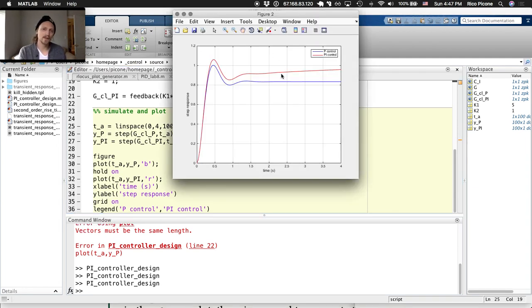Yeah, so it's going to 0, but it's slow, right? The transient happens and then it slowly oozes back to 0 steady state error, probably at time infinity. So we have success: 0 steady state error, and transient response performance that we started with, which is about 20% overshoot. So that's all good, but we might say we'd really prefer to settle to our steady state value a lot quicker.